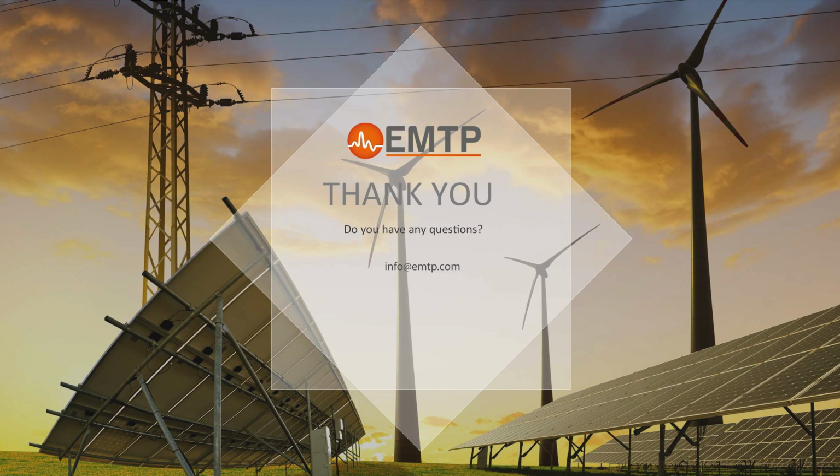So we have done it for three or four contingencies, with up to 2 or 3 PV plants at the same time in the system. And the cases that you're analyzing are usually a relatively weak grid. Do you remember what the short circuit ratio was for this case? I'm not particularly sure about this one, but usually we try to get it to around 2 or 3. Yeah. So usually with lower SCR, it's highly likely that the PV will oscillate. The similar behavior that I showed you is very likely with the lower SCR.